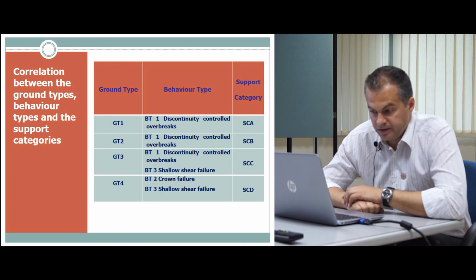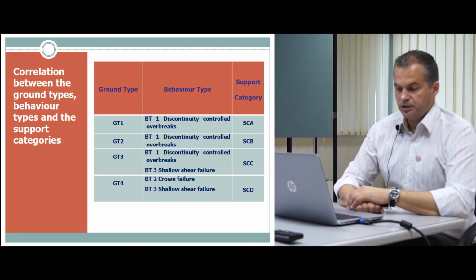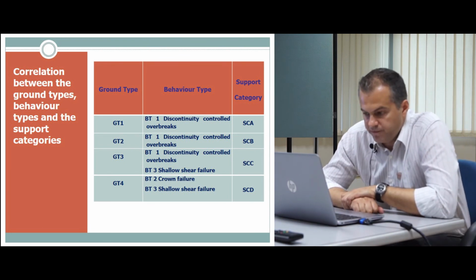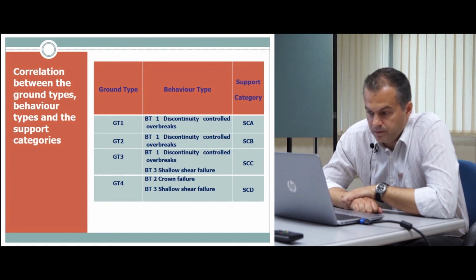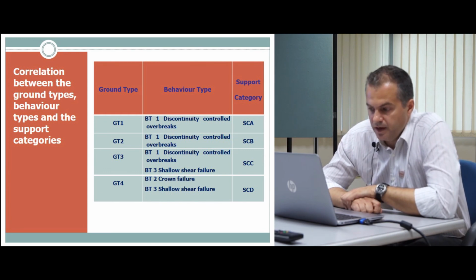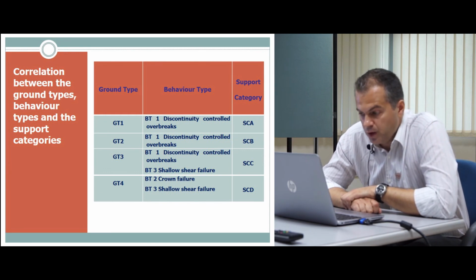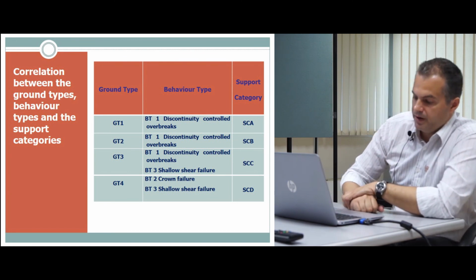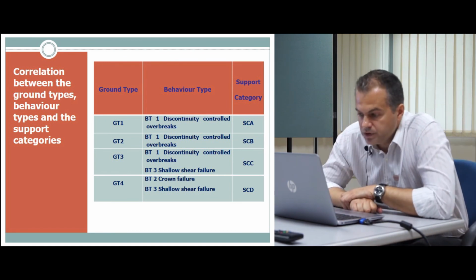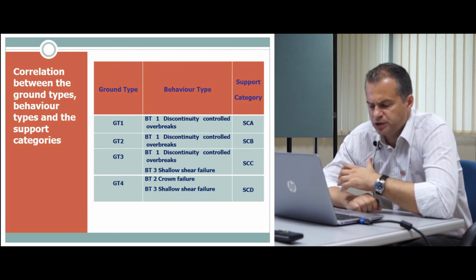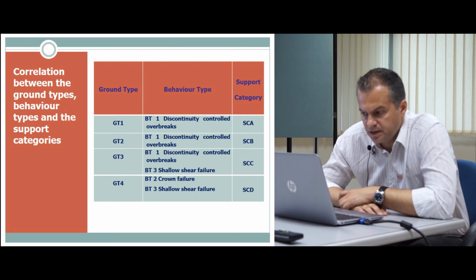So starting from the first case, just in order to keep these wedge failures, you need some thin shotcrete, not very thick, reinforced of course, and Swellex anchors, because you have the siltstone layers, you have this immediate wedge sliding and falls. No steel ribs would be needed here, and a larger excavation round could be implemented.